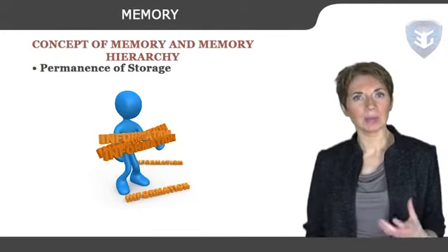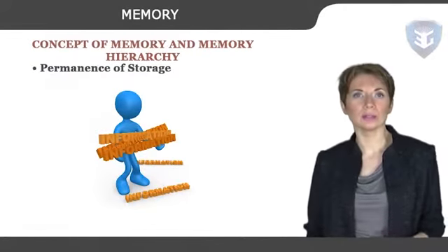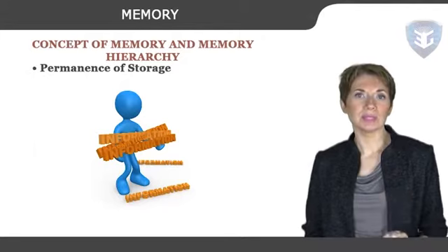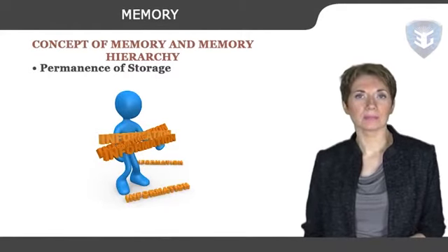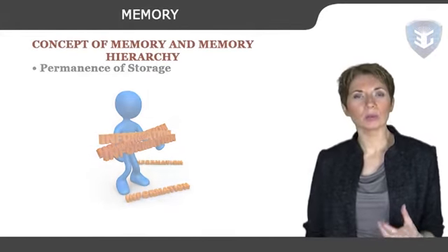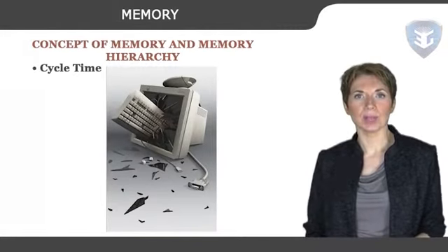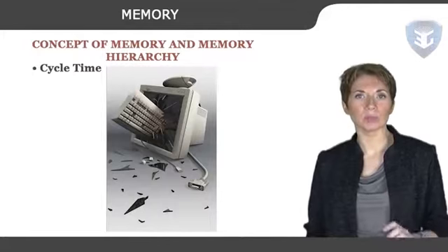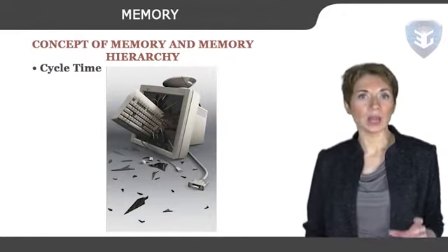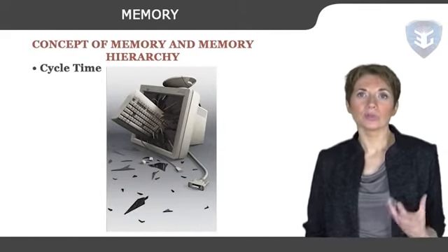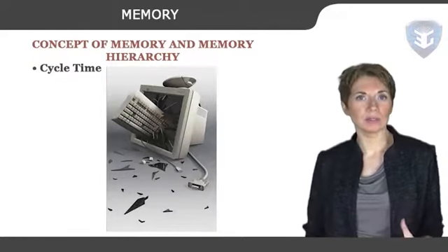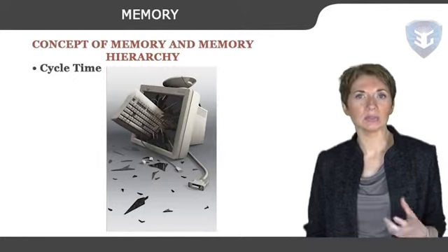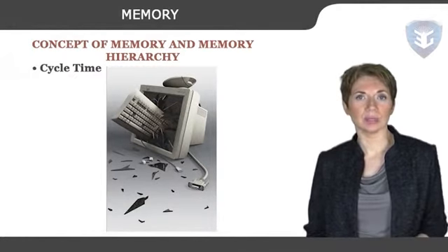There can be some memories where the stored 1 loses its strength to become 0 over a period of time. These kinds of memories require refreshing. Cycle time. It is the minimum time lapse between two consecutive read requests. Is it equal to access time? Yes, for most of the memories except the ones in which destructive readout is encountered or a refreshing cycle is needed prior to next read.